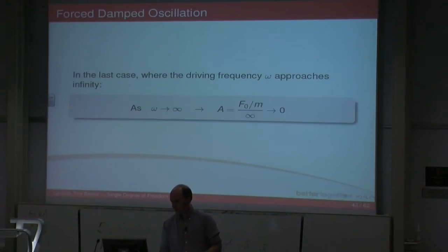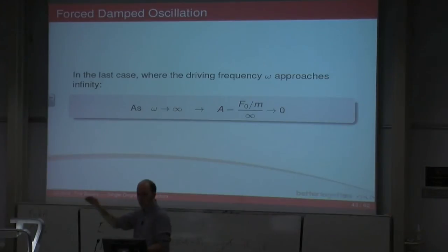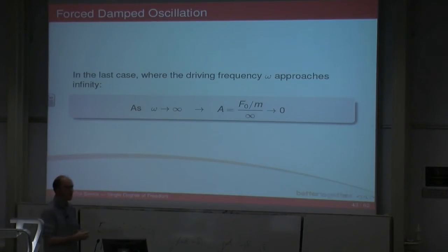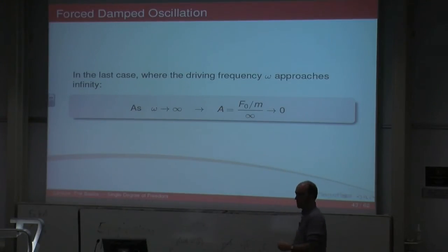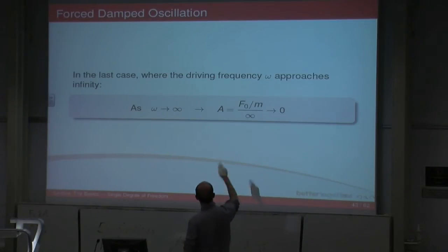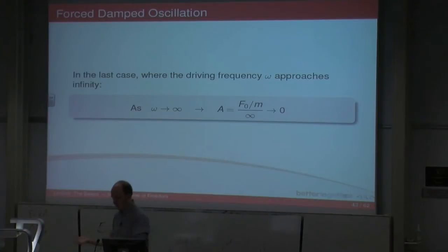What about the last case, where the driving frequency approaches infinity? So I'm shaking it really, really fast. If I'm shaking it so fast, do you think the thing has even time to respond? The answer is no. If you think about it, if you're shaking something so fast, it's not actually going to respond to that movement. And so your amplitude actually drops down to 0, approaches 0. And that makes sense. If you stick infinity in the denominator, anything divided by infinity is 0. It's tiny.